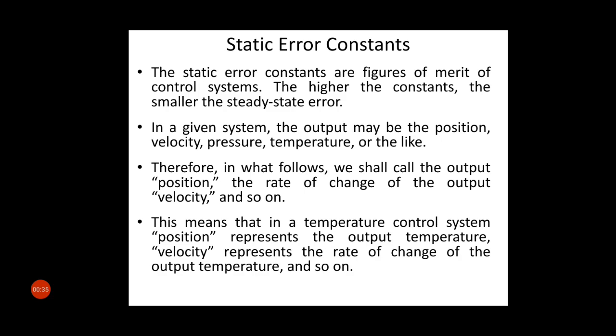So whatever control system we are exciting with a standard input signal may have steady state error as 0 or constant or infinite, and that steady state error depends upon the type number of the system and the input signal.